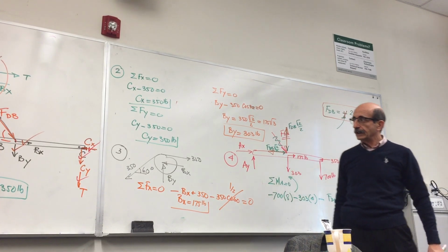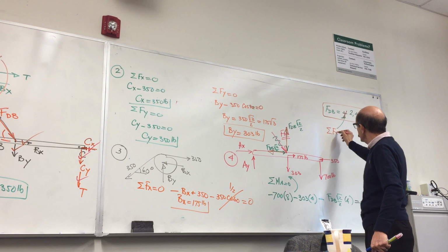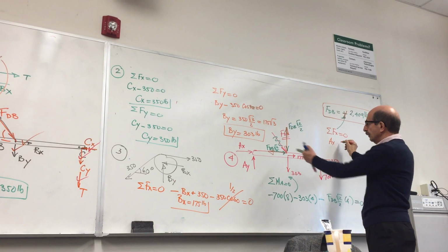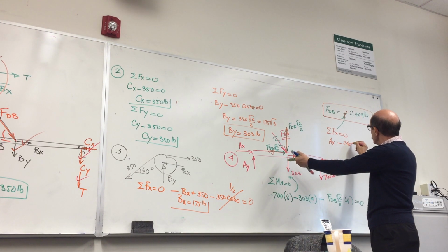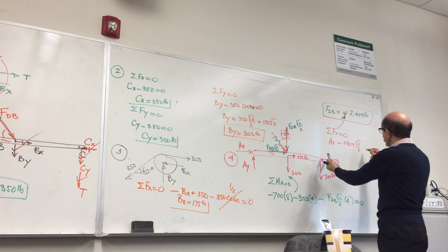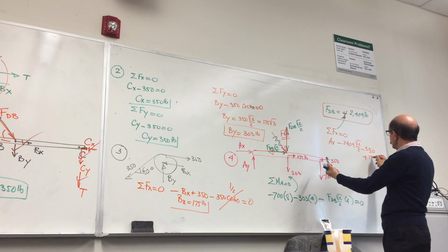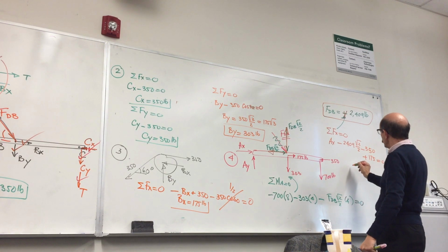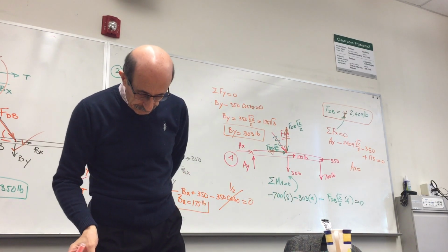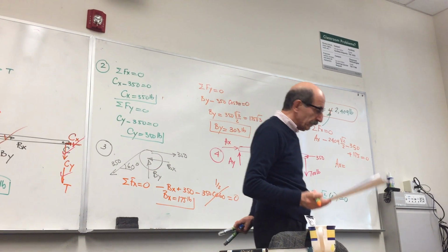Again, as you can see, of course, I can now solve for summation of forces along X equal to 0. So I have Ax minus 2,409 square root 2 over 2, minus 350 plus 175 is equal to 0. Ax comes out to be 1,880.